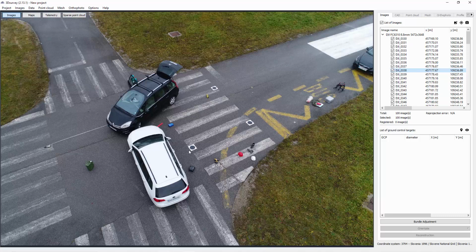Important is that you place those targets on a horizontal level, so you need to find an area which is horizontal. Targets need to be perpendicular, and we defined a 3 meter distance between them. It's good enough for us to deliver accurate data. Nevertheless, if you have a GNSS system, or for example a laser scanner, and you do a scan in addition, you can use all that information also to do the orientation. But today we will do it with this approach. You will see this a bit later on.